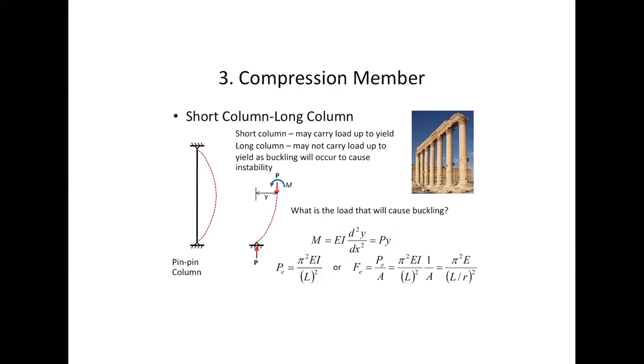And notice that I mentioned in the second clip that when you have the two axes of your cross section, your compression member always bends in the direction that has the weaker moment of inertia, because it has equal length, right? But we can say that when we change this into the critical buckling stress, this becomes a term that we always refer to as the slenderness ratio. Okay, slenderness ratio. The more slender the member, the less load carrying capacity it is going to have, and it's going to buckle much more easily.